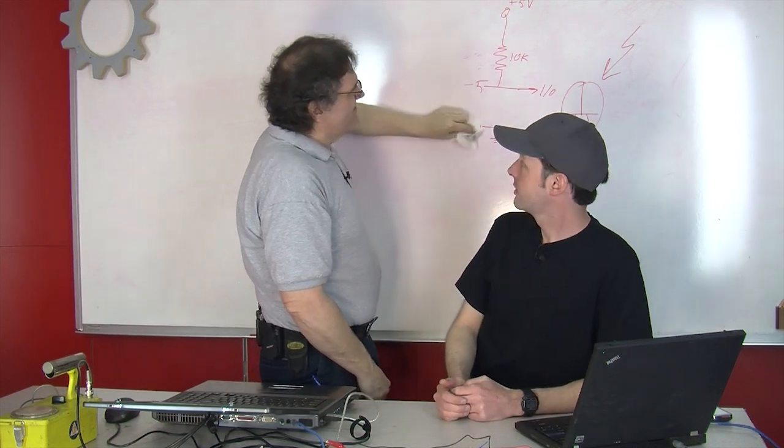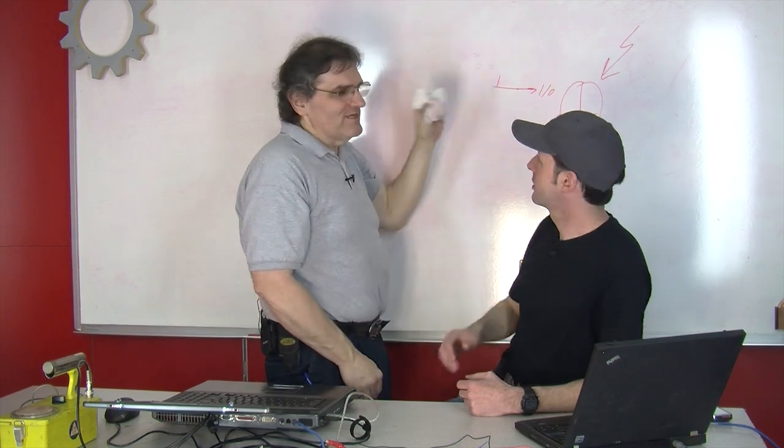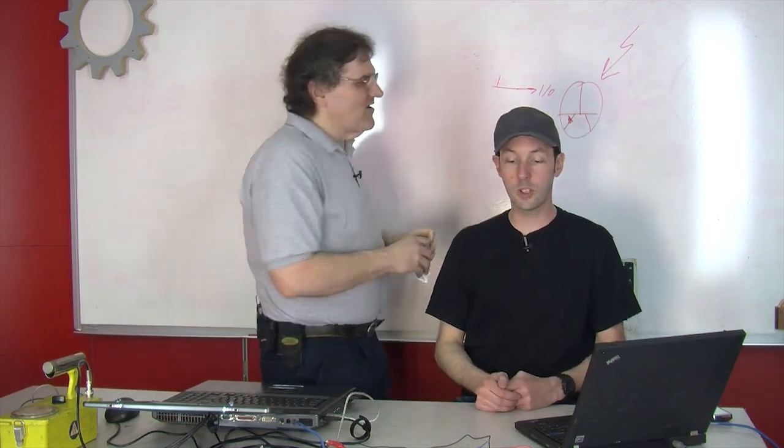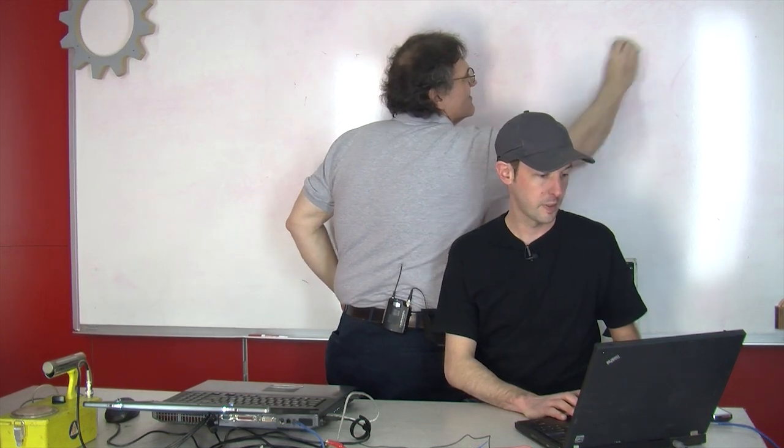Now the I/O pin, which is this last little bit over here, we're wiring into pin 2 on the Arduino. They count from 0, so it's like the third socket, but it's 0, 1, 2. Now, pins 2 and 3 are interrupt inputs. Now, when you get a gamma wave or a beta particle in here, it grounds the tube, you get a negative spike. So that's an event. The transition from its normal voltage down is the event that we're going to try and track.